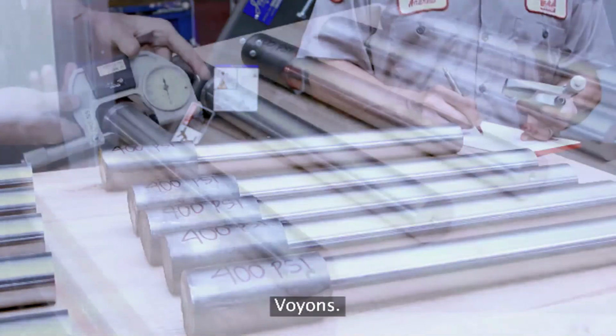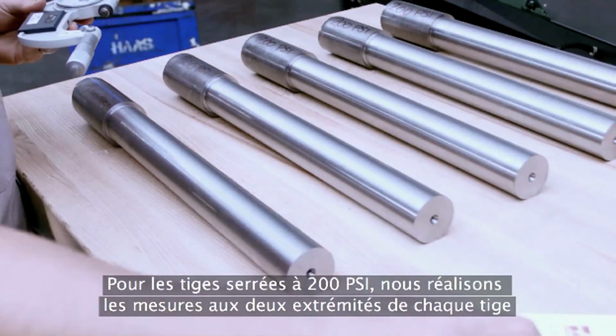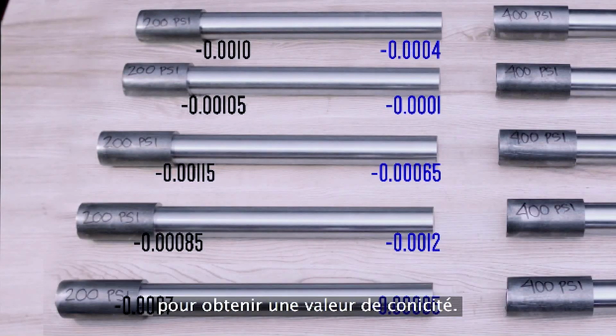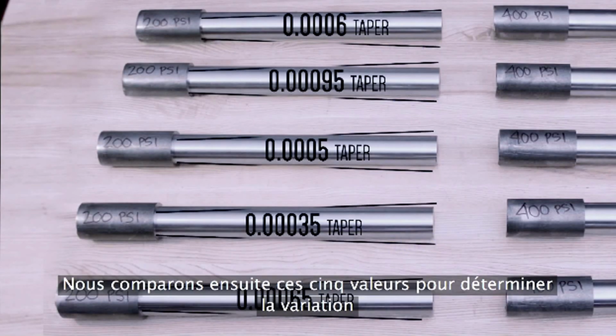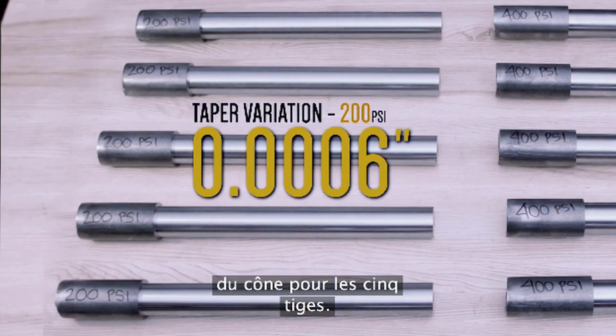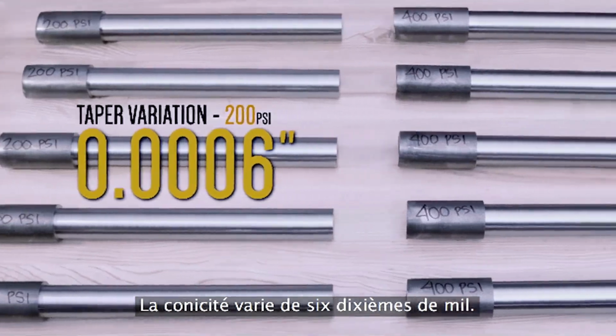Let's see. For the 200 psi shafts, we take measurements at both ends of each shaft to get a taper value. Then we compare these 5 values to find how much the taper varies for all 5 shafts. The taper varies by 6/10.